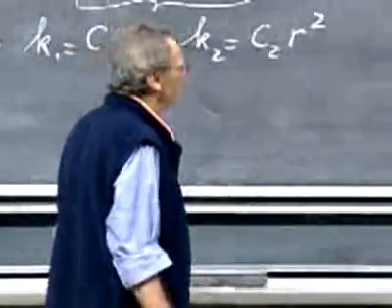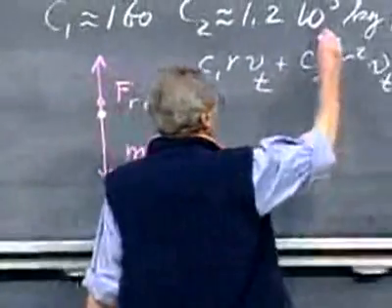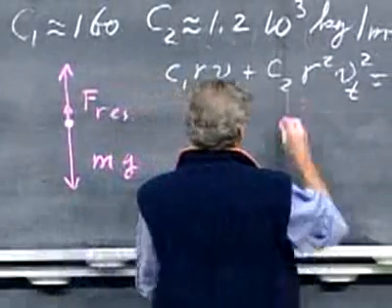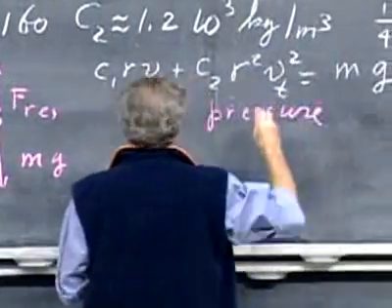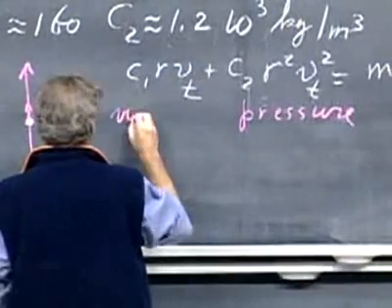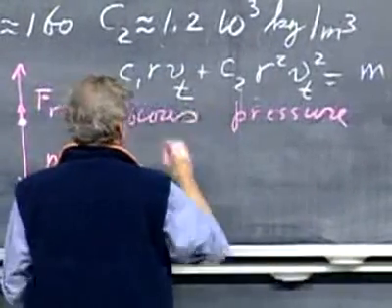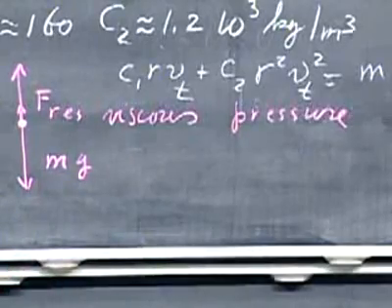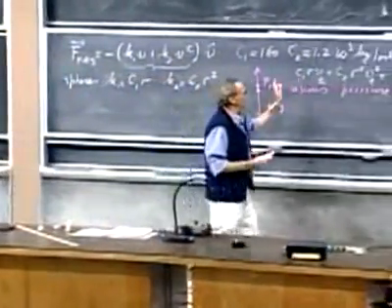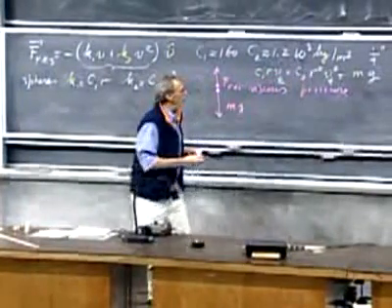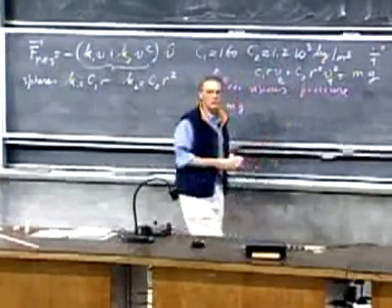And the reason why that would be silly is that I claim that this term, which by the way we call the pressure term, that this term can be completely ignored compared to this term, which we call the viscous term. How do we know that that pressure term can be ignored? Well, let's first ask the question, when is the viscous term and the pressure term the same?